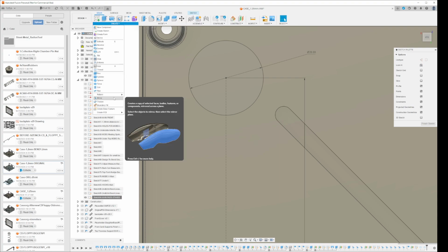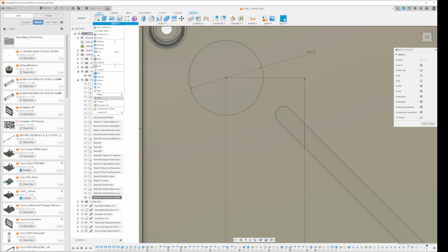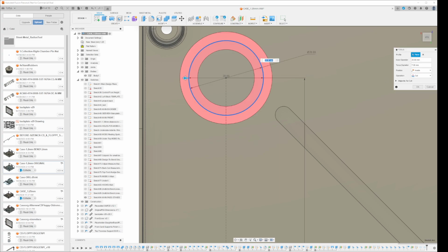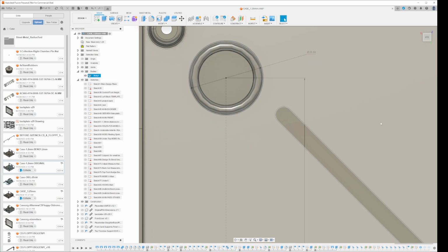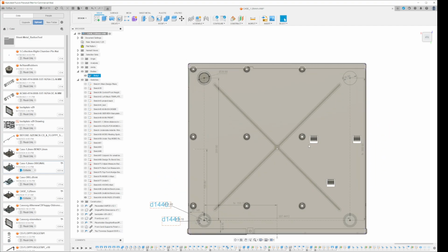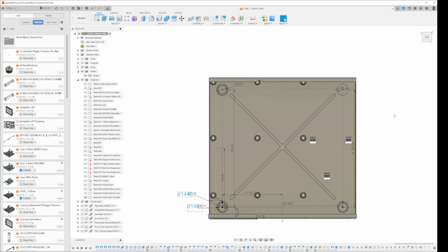Solid, create, torus, to the line. I do exactly the same thing I did before. Bring in the value, change it to a join. If for any reason at all, it should be correct now, I can flat pattern this with this in place.